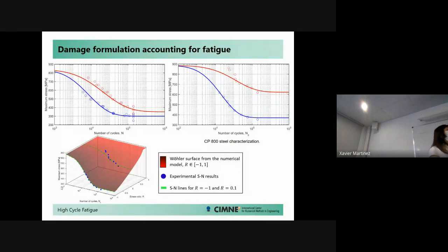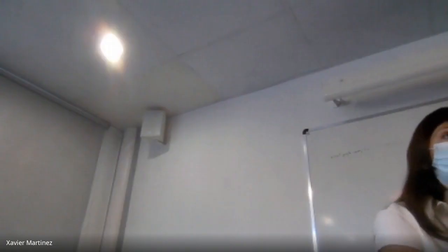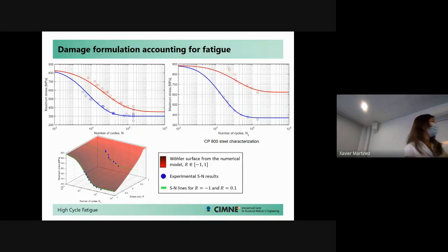But once I change the load because I'm interested in variable amplitude loading, or maybe I have some damage effects inside our model and I have a crack that has to propagate, so you'll have stress redistribution. What this means is the stresses will change. And that means that possibly the reversion factor is going to change. So if you only define that discretely, these specific reversion factors, you have the problem undefined in between. And that's not good if you have an undefined problem, okay?